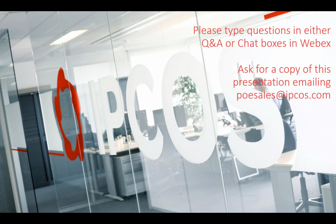So what is the difference between using a PCT in the base layer and a PCT in APC? That's a very interesting question. The difference is that with APC, you're controlling with a multivariable approach. So with APC, the handle that you're using to control your PCT may not always be used to control your PCT, because there may be some other constraint in the plant that the APC needs to react to. So it will not be a continuous control of your PCT.